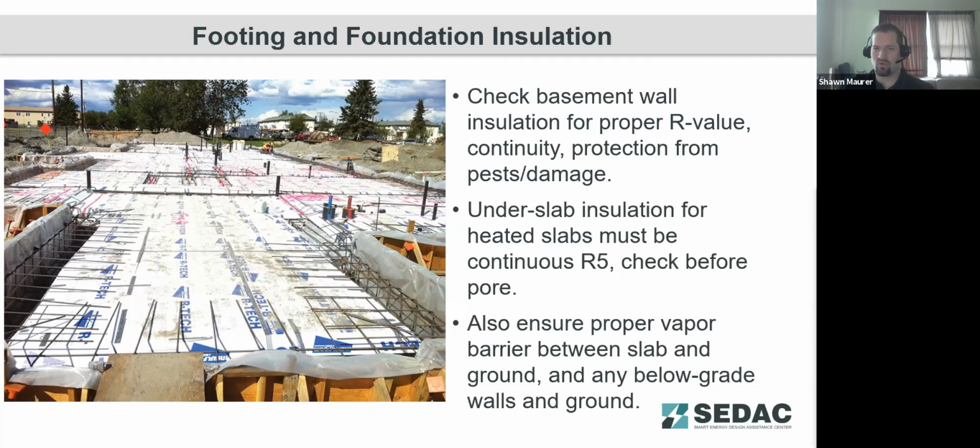Another thing that's very important is that you've got a proper vapor barrier between that slab and the ground, so that you don't have moisture wicking up into that slab, which can then impact comfort and humidity control within your building later on.